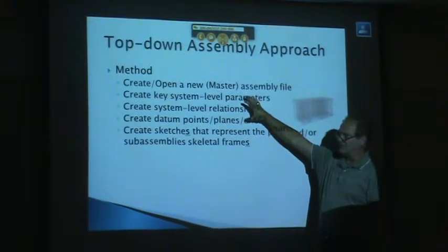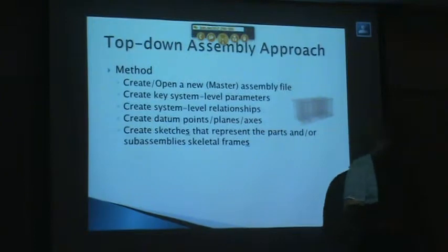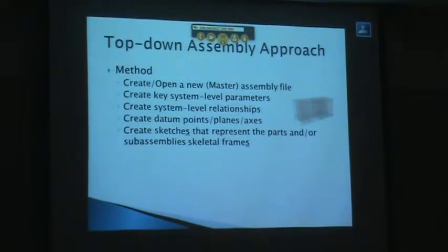In addition to these high-level defining things, if there are some sketch objects, lines and arcs and other sketch geometry that you want to be the backbone, the skeletal frame of the human body, if we were modeling that, you represent not a full-size rib with a cross-section, but you represent that curve that represents the center line of a rib. Okay? So you represent very simple, very basic lines and arcs, and you do it in a sketch-based environment at the assembly level.